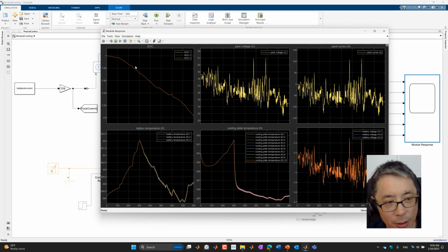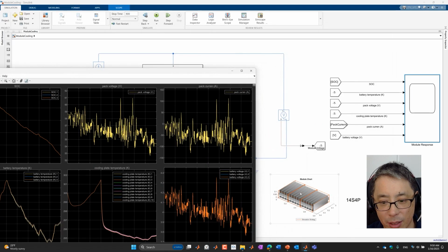And the top left plot is the SOC. So you can see we have 3 lines. For a short drive, 800 seconds on the highway, the pack SOC dropped from 100% to about 90%. The 3 lines almost overlap, meaning we don't see a lot of gradient in terms of SOC, which kind of makes sense. Those 3 boxes are connected in series, so we don't expect large difference in SOC. And because, like I mentioned, we defined the grouped strategy for the model resolution, we have 3 models. That's why we are seeing 3 SOC curves.